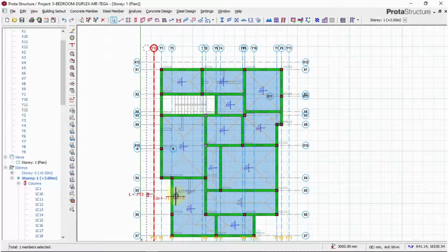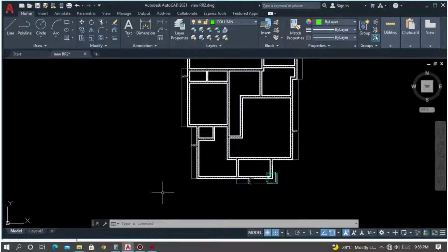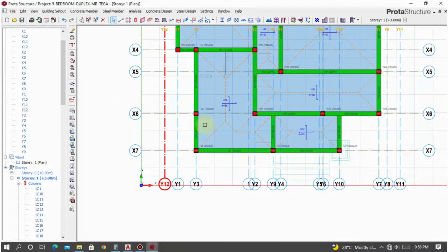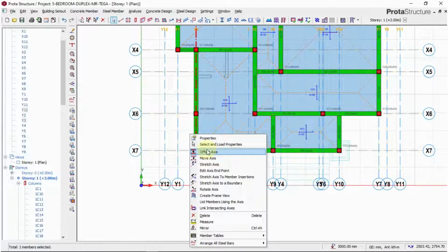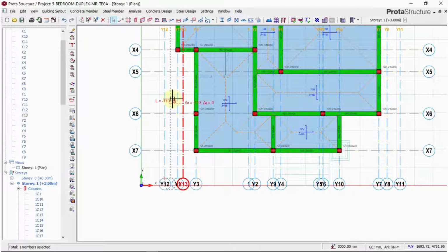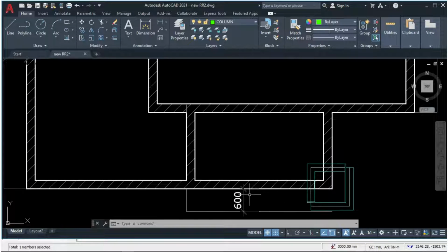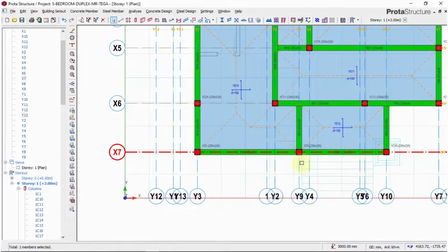The same thing happens when you're going down. Do we have a cantilever at this area? Let me see. Yes, we also have a cantilever at this area. So the same, we offset this. 713, enter. Then we also have a cantilever at this face. Yes, we have a cantilever at this face on the balcony, on the veranda area. So we'll also offset this. We are going down, we also use minus. So you press F2 key, minus 713, enter.